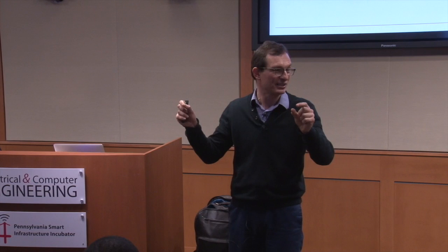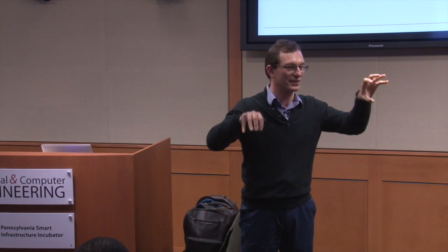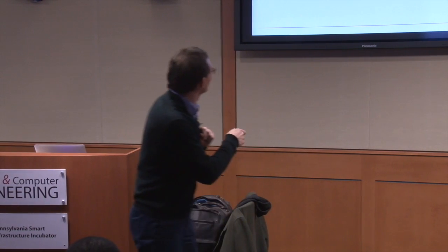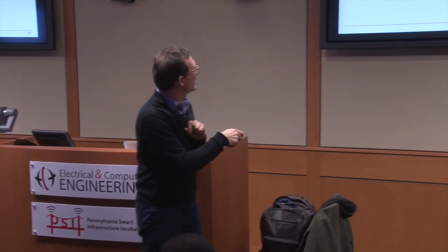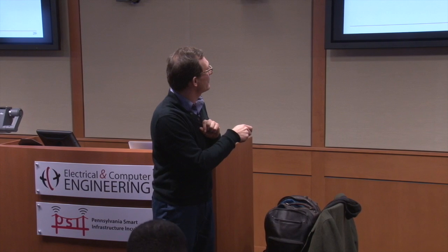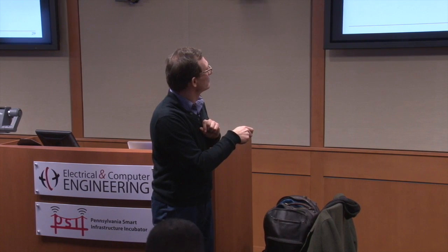It could be immediate. It could be another register. Now your addressing mode is immediate addressing mode and register addressing mode. There are 2 different addressing modes. And the way you pick which addressing mode is used is that bit that's steering you. Make sense? Okay. Let's cover the data types first, because this also affects the complexity of the ISA.